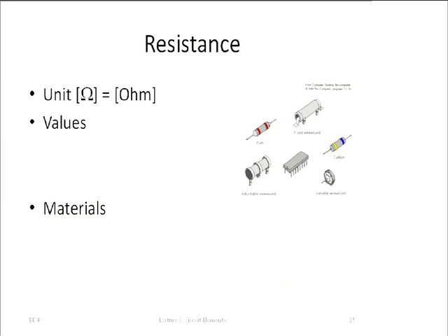What happens if you want a resistor that has a very, very high value? It's actually a very interesting thing in the laboratory. When you touch the component, your hands are a little bit sweaty. Okay? What is sweat made out of? A little bit of water and salt, right? Water and salt, that's ions, that's actually conductive. So you pick that component, you put the thin film of sweat on it, and current can flow through it.